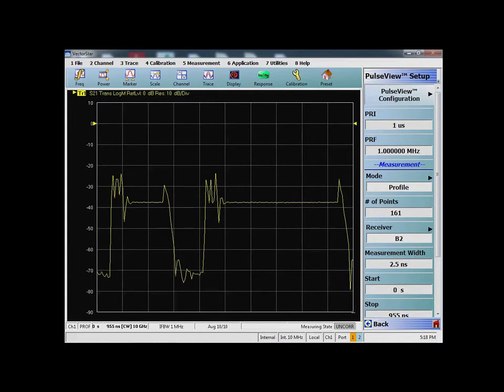The same thing is actually applied when you have a pulse modulator test set. The only difference with a pulse modulator test set is that the reference, the A1 receiver, which is the first reference receiver that we have on the VNA from the source side, will also be a pulsed one.